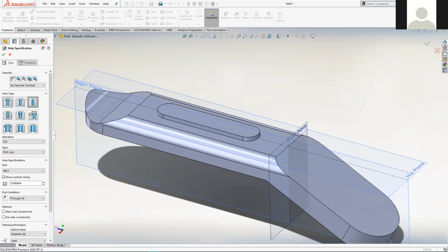That indicates the top of the thread form. The thread form is a number of little spiked teeth, or spiked teeth with the ends chopped off, and they fit within that little gap between the dashed line and the actual hole itself, or the actual drill size that created the hole initially before the tap went in.